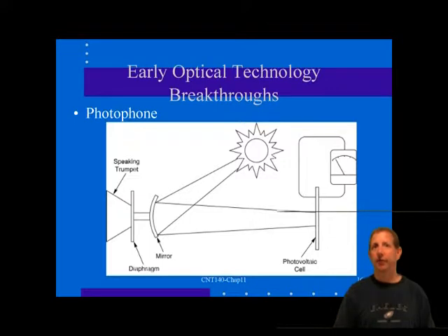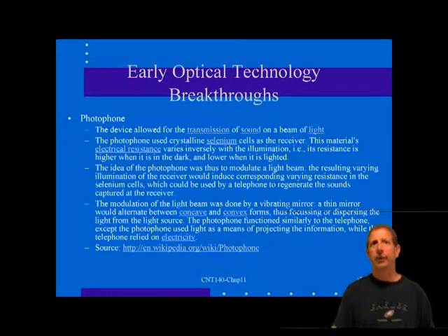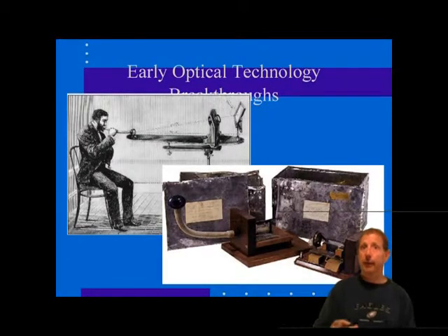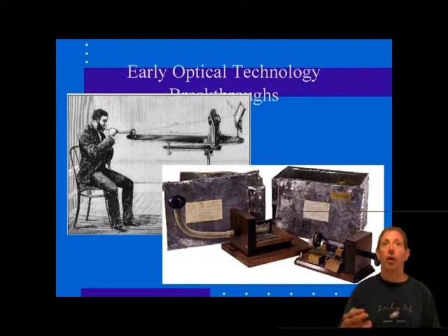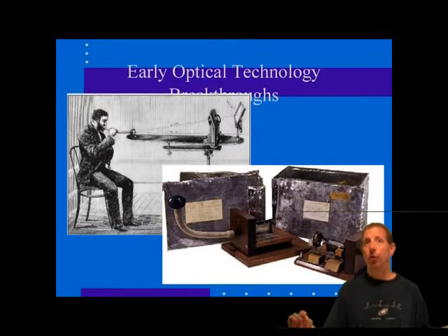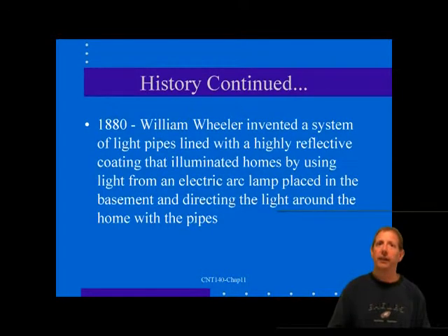Most fiber optic interfaces are technically simplex connections, that is, either for transmitting or for receiving, but not both. Two interface connections, one for transmit and one for receive, are required to make a complete connection. This two-connector arrangement forms a duplex connection. The optical connections to an equipment interface are thus paired and are usually marked TX or RX, or T or R, for transmit and receive, to indicate the transmit and receive directions respectively. Taken together, the transmit and receive optics are called an optical transceiver.